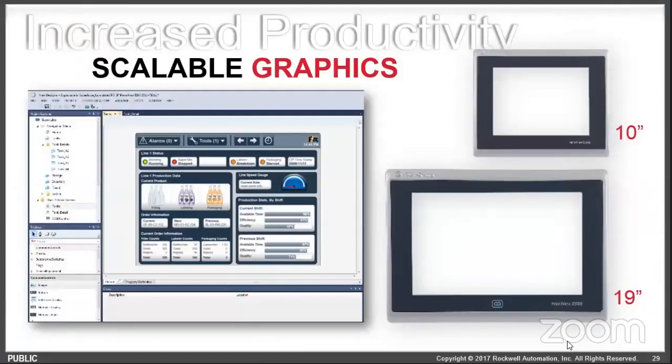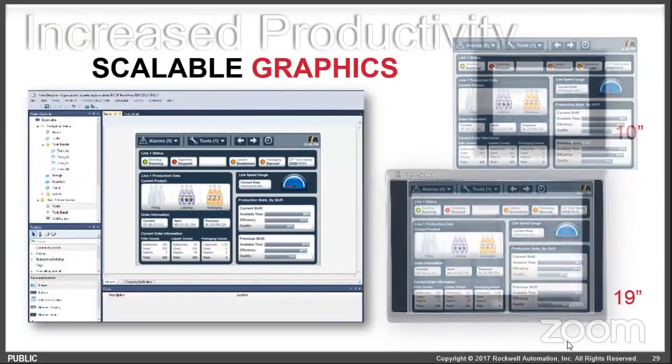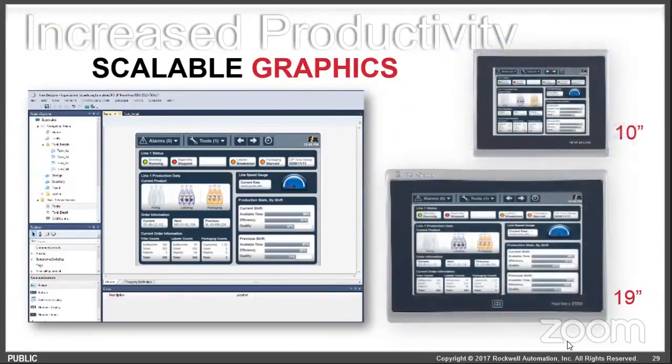Something that's a little bit different as well is how graphics are actually rendered on the panel itself. So you have View Designer there, you're making yourself an application, and because these are scalable vector graphics, you can take that same application and put it on multiple different size screens, and it's going to properly scale. Whereas before, if you took a 10-inch screen application and tried to put it on a larger panel, it would stretch, and when you take a bitmap graphic and stretch it, you get a lot of jagged edges around graphics, or the other way around, it looks all squished, and nobody wants to have to make the application twice. So do it once, and you can move it to different size panels.